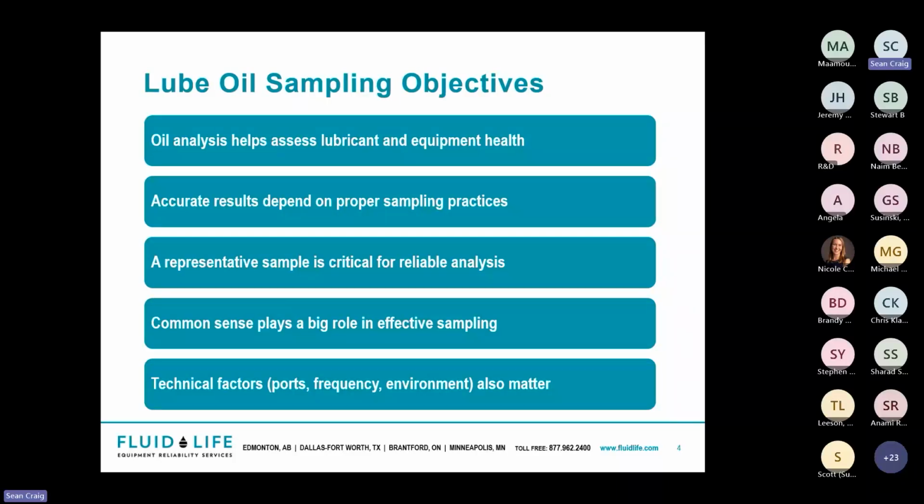These obviously can help reduce downtime and improve reliability. If you didn't have this data, it could get you to some incorrect conclusions and decisions that may cost additional time and money, where you went one way, but really it should have been the other. Or instead of draining 10,000 liters of fluid, all you really needed to do was hook up a filter cart to remove the water, and presto, you're good to go. So, saving time and money on situations.